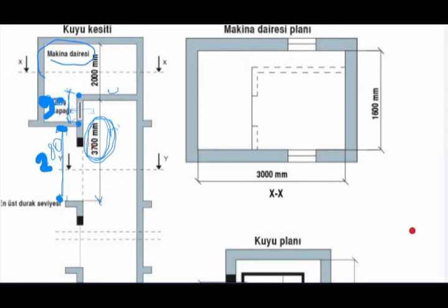And the reason is that if we look at this rule, which should be 3.70, okay? Because the elevator is supposed to come till here, okay? The cabin of the elevator. Then on top of the elevator, you have many tools, materials, and cables and everything. That is why here should be the last floor you have on this part. With this one, it should be at least 3.70. So if you have 2.80 on this box, here should be 90 centimeters, okay? So, or if it is 3 meters, this part